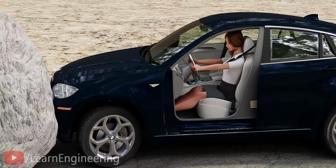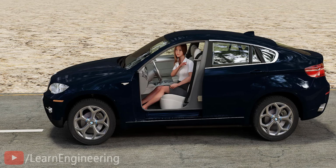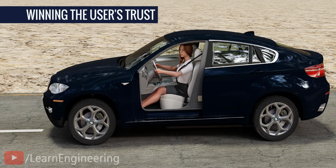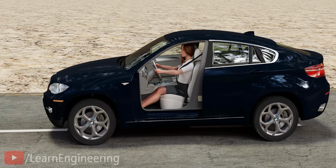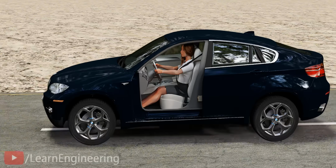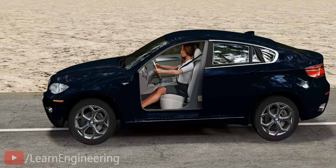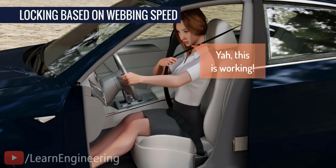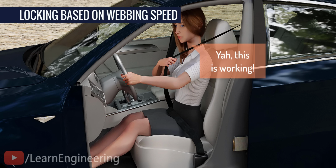In the early days of seatbelt development, it was quite important to win people's trust so that they would use seatbelts regularly. The ball movement technology we just discussed is a perfect one, but a common man cannot test this mechanism. So, engineers came up with an interesting idea. Develop one more mechanism which is based on the webbing's speed. If the webbing moves fast, it should lock. If not, it shouldn't lock at all.